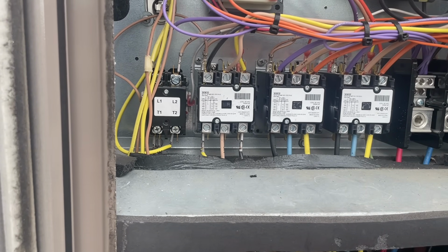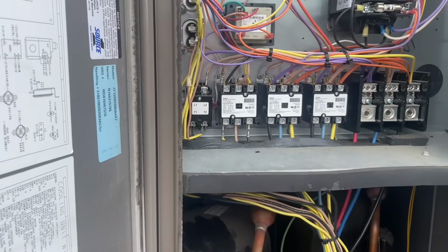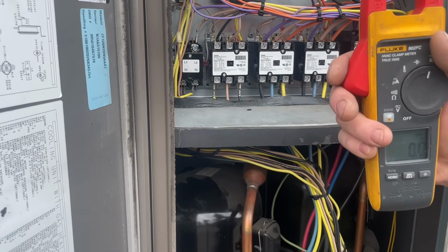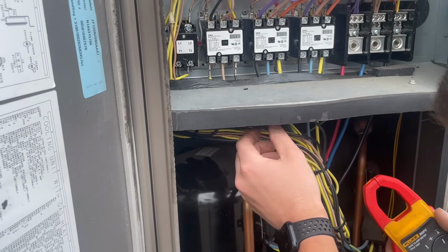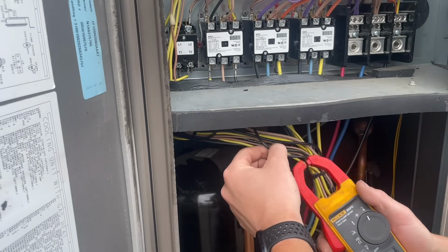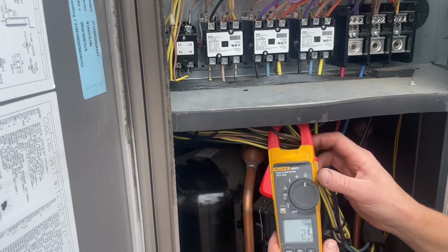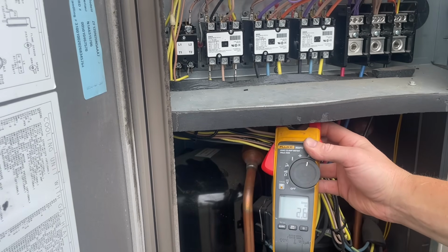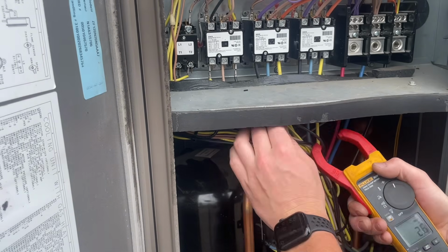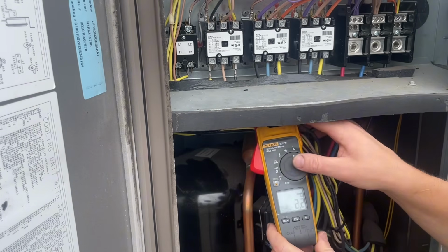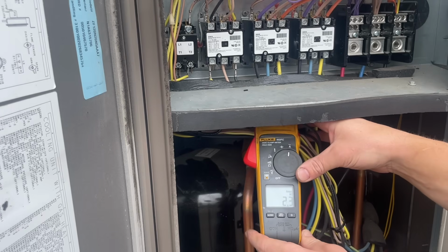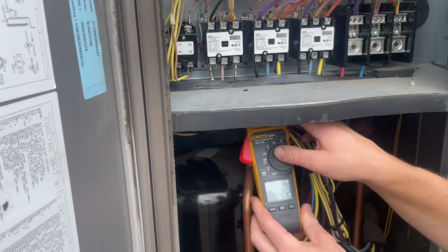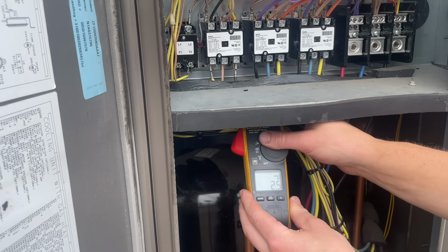So there's 2 ways we can check this again. One is with the airflow, but I'm going to show you the amperage method first. I'm going to pull you guys back. So we're going to take those same 3 leads that we just read, and I'll show you the difference. We'll take our black lead, which was our highest lead. So look at that. We're only drawing 2.6 when we were drawing 3.5 amps before. This lead, I believe, was 3.1. We're drawing 2.3 amps. And our yellow lead, we're drawing 2.5 amps.